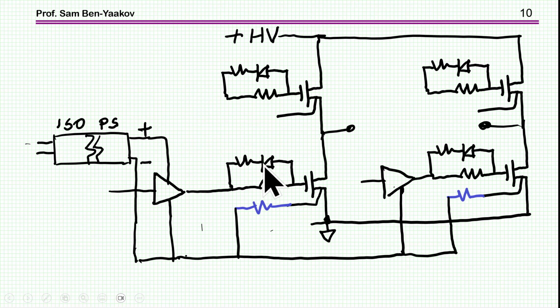This problem also appears in the case that you have a bridge and then you have two low side transistors. They may also be parallel to other transistors, but let's just talk about one transistor on each side. Now here again, you'd like to use the same power supply for the two sides because obviously this is the same line, the same potential here for these two. But again, without this resistor, you may have quite a bit of a circulating current here. So you better put some resistance here in between. And again, you have to adjust for it in the actual drive side.